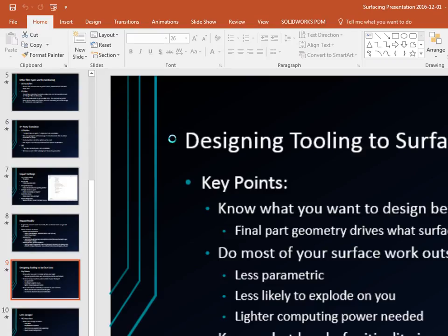So yeah. Let's see. So I've got my top surfaces here. Basically, I want to make a continuous surface out of this that I can actually utilize for a single extrude. So I need to extend out some faces. I need to go in between faces. So I think this is a good time for me to talk about, I've got 3 main ways of extending out faces. And my preferred method is untrimmed surface.